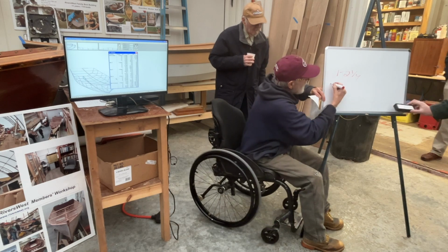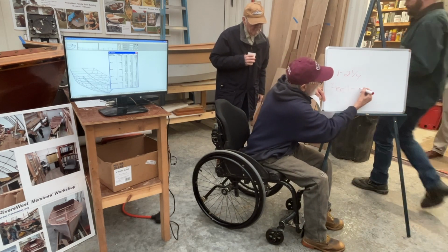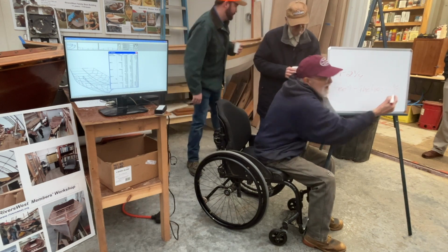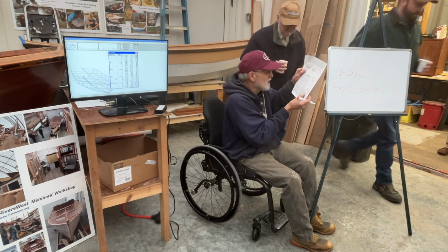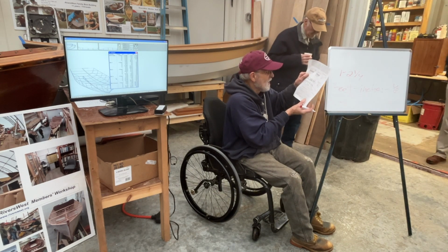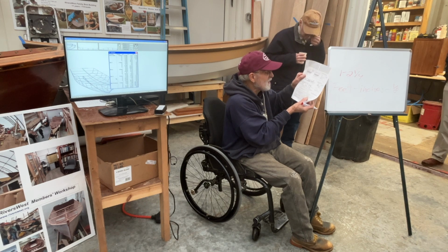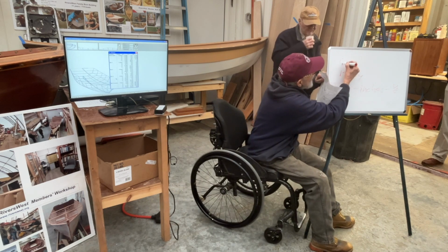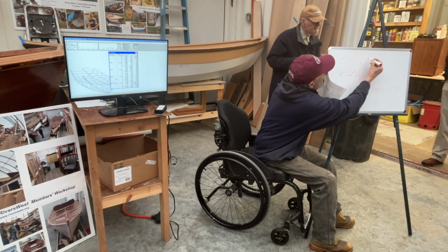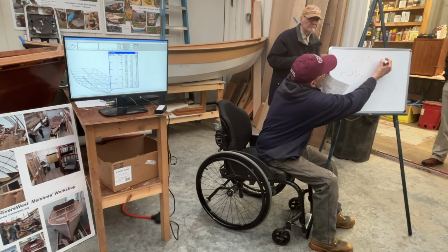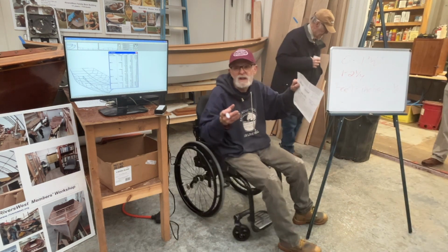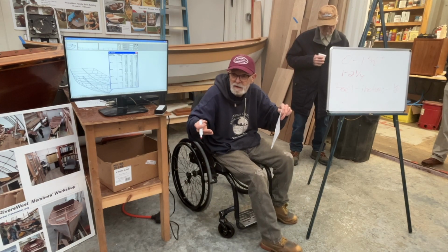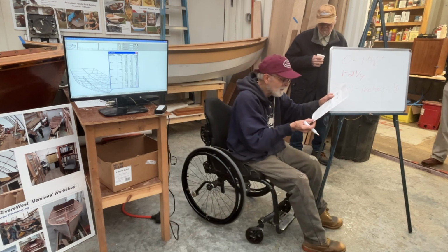Typically, they give it in feet, inches, and either eighths or 1/16. But if you look at station number 2, the second line, it's 0 dash 1 5/8 with a plus. That's a way to indicate less than or more than an eighth. It's a 16th.